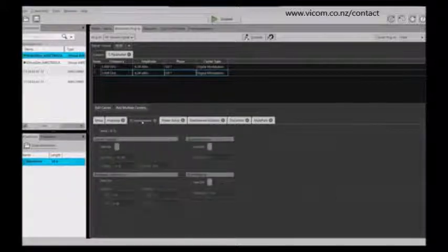pretty easily. So we also give you the capability of turning on some IQ impairments, and this is very useful for receiver testing, such that you can build your waveform such that it will give you the worst case condition for your particular receiver requirements. And so you can swap the IQ, see if your receiver can handle swapped IQ patterns.